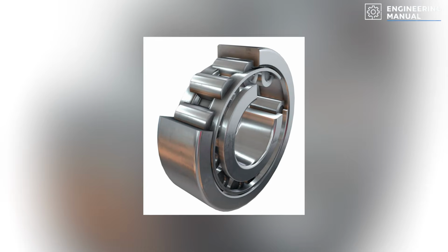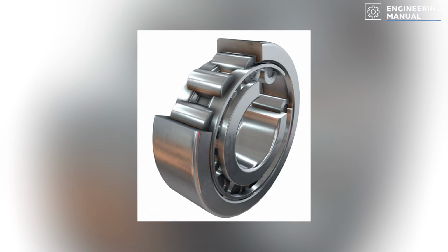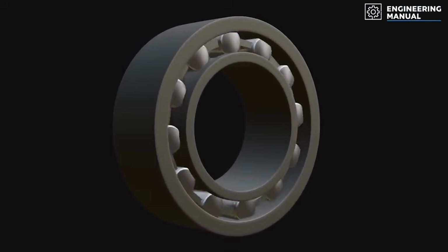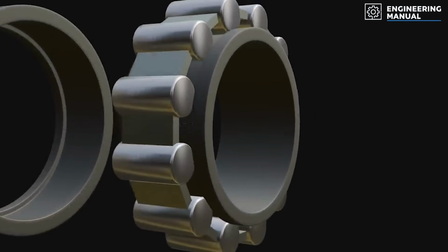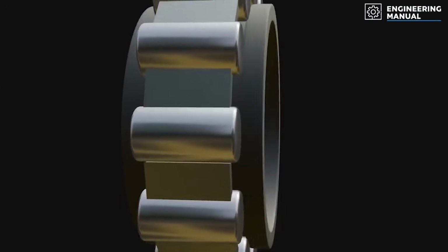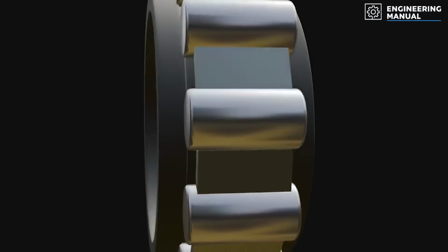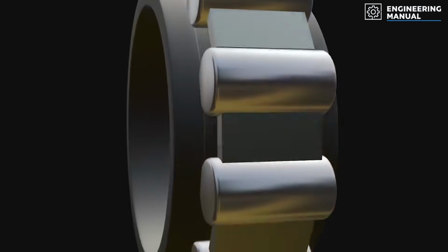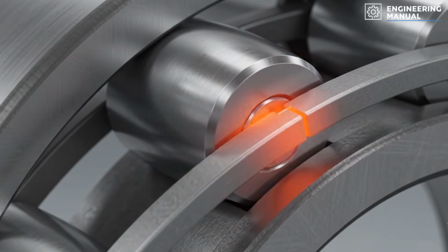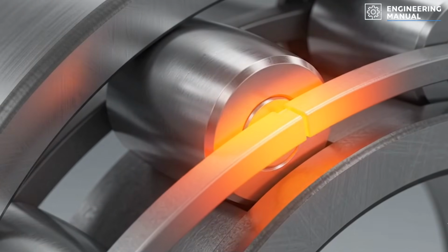Roller bearings also generate more internal sliding than many engineers realize. At high speed and light load, the rollers can skew slightly out of alignment with the raceway, and the cage itself can begin to slip rather than track the roller set exactly. That skew and slip translate directly into friction. That extra friction becomes heat.